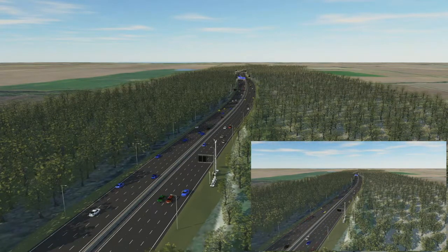We had similar problems actually. If there is no gap when we are trying to do the visualization, there is a color bleeding that happens when we are running through. So we are trying to make it into only solids so that it is useful in visualization as well as for any clash detection also. Yeah, that was an issue we had.